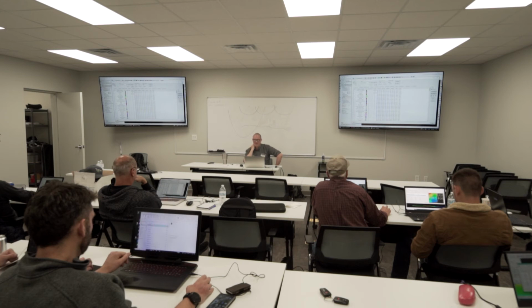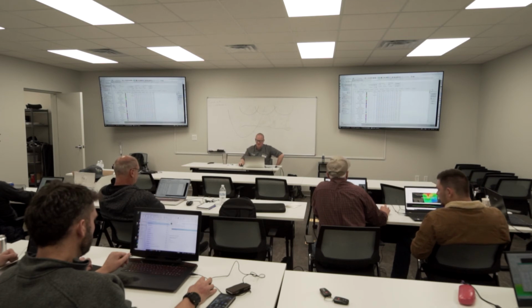Yeah, so I went to about 20 million points. So we got 20 million ground points and roughly 22 million non-ground points. But the general thing that I like to think about is you want this automatic ground classification to do like 95% of the work for you. And then we're going to go through with some manual cleanup tools and some manual editing to put the final polish on it. So at this point, what you want to do is use some different visualizations and different inspections to understand what your ground class looks like.